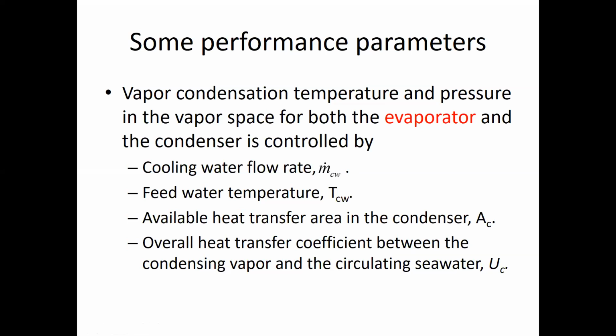Definitely, in summer, the temperature is about 28 to 30 degrees centigrade in the Gulf. In winter, it can go down to 13 to 15 degrees centigrade. So the performance of the unit is going to be dependent on how the weather temperature is affecting the seawater temperature. This is going to affect the system performance, unless you have something to do there, I mean, to remedy for this.